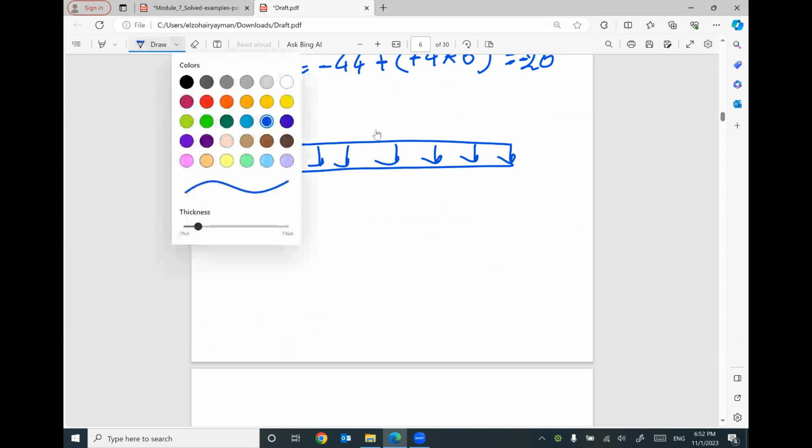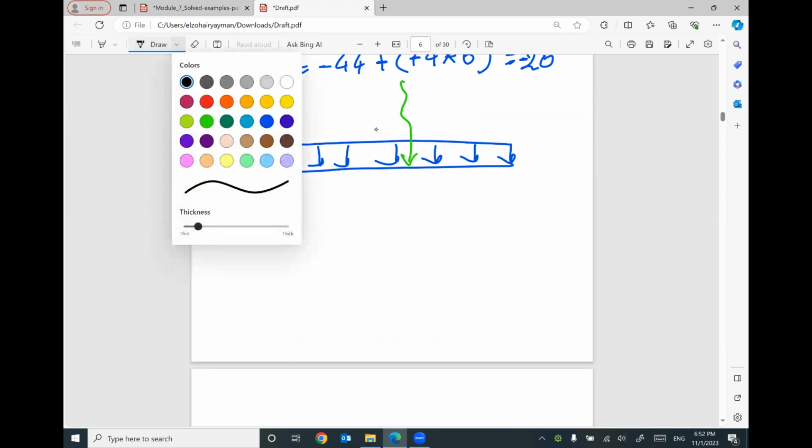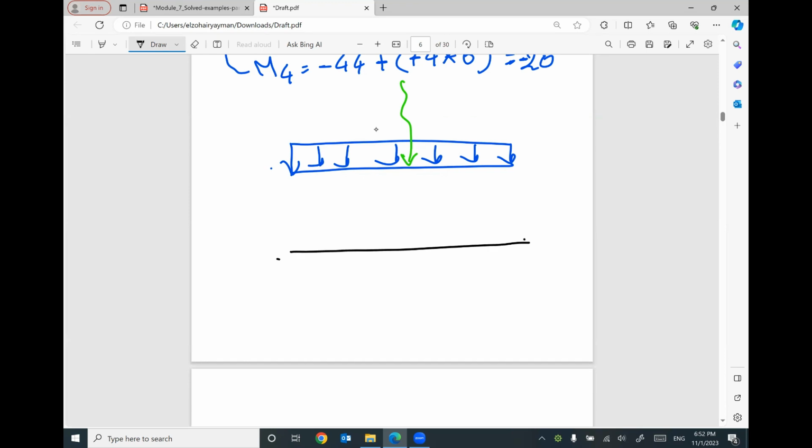That means I will have equivalent. So if you would like to draw your shear force diagram, assume we have a value here. I will move dotted inside the distributed load. I have this equivalent moving down, so I'm gonna move down maybe until 0, maybe after 0, maybe before 0, I don't know, based on the case. Then I will move forward to the end of the distributed load. So this is the start of the distributed load. This is the end of the distributed load. I'm gonna draw solid line in between.